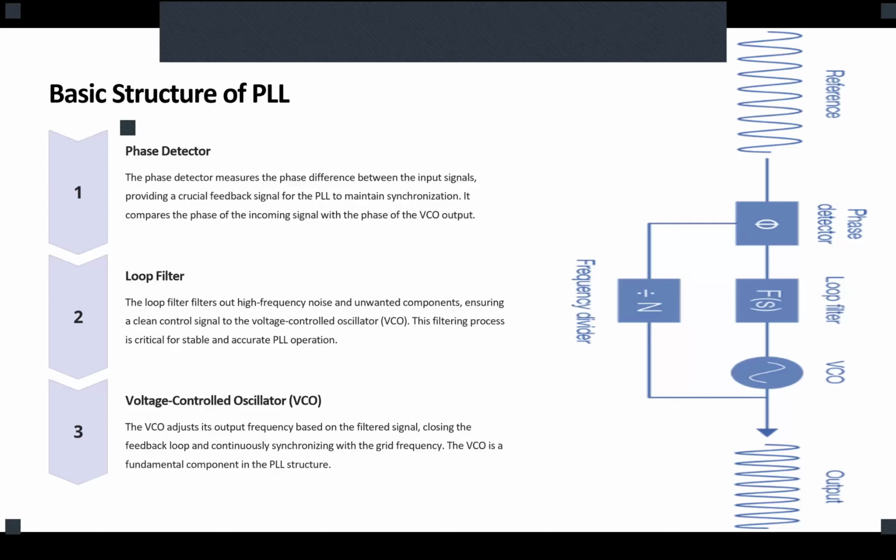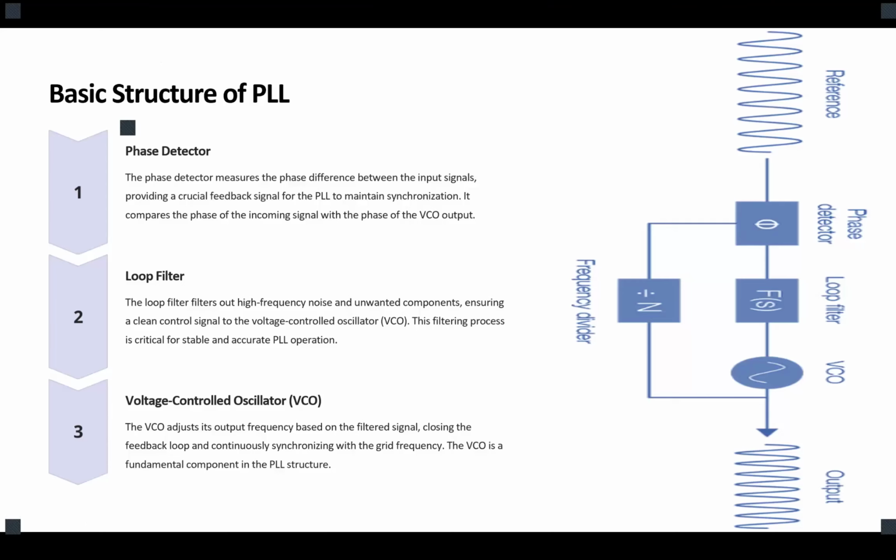Before implementing a PLL, you had a sinusoidal voltage source in your PWM system. Now that you want to apply a PLL, the PLL should define that sinusoidal voltage. It's not the same, because the frequency of the grid is changing.